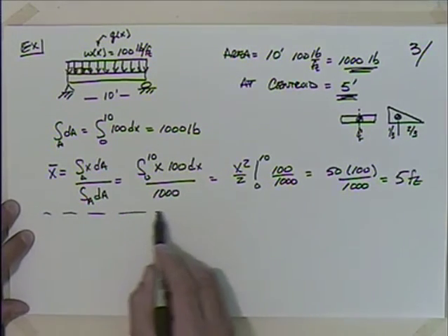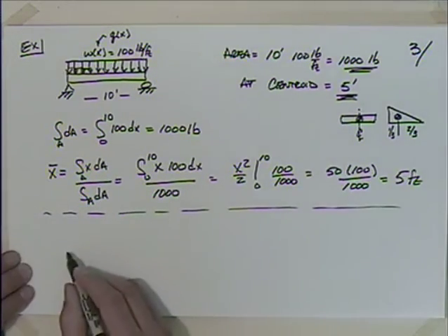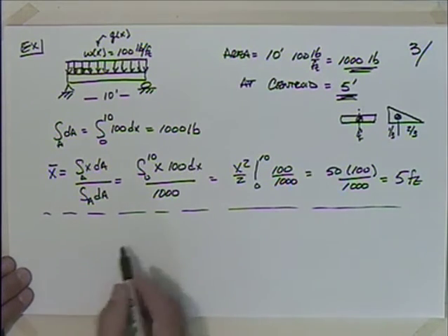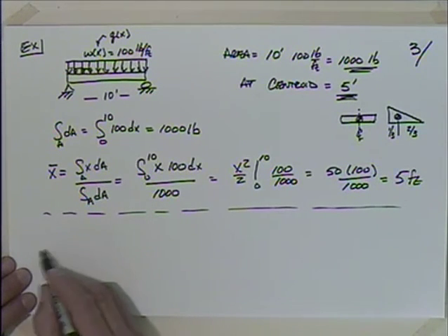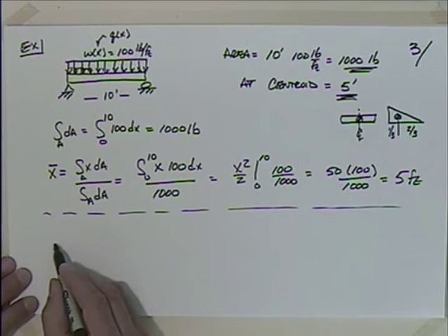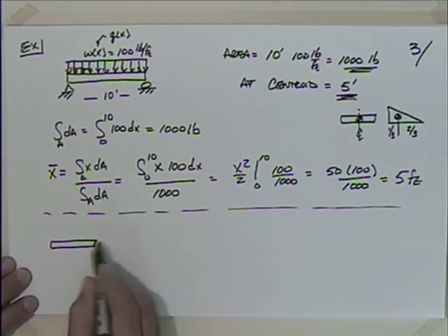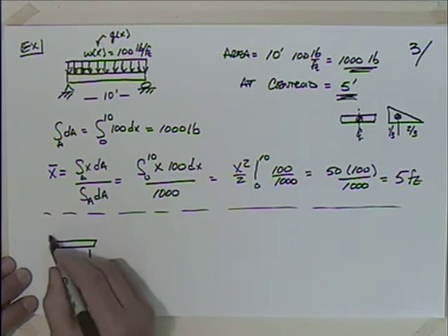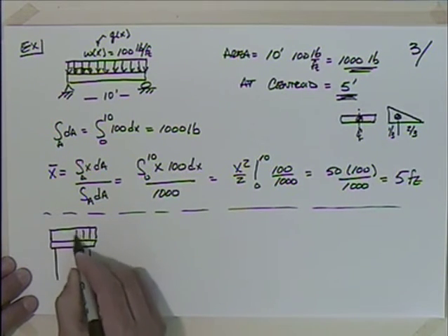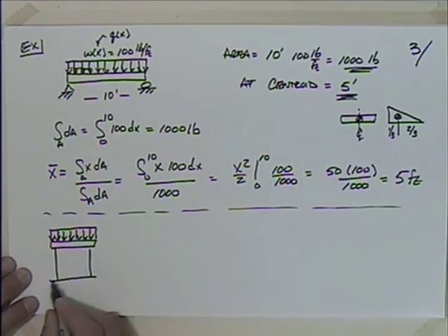Where do we get into that? Certainly a lot of times with snow load, we'll try and use some simplifications. Like we started out our discussion with, if we just have a flat roof, we're probably going to just take a constant load like this, so we're not going to be doing a lot of calculus with that.